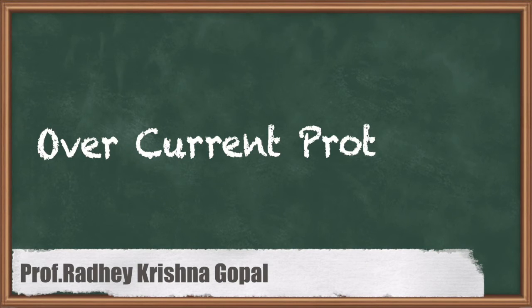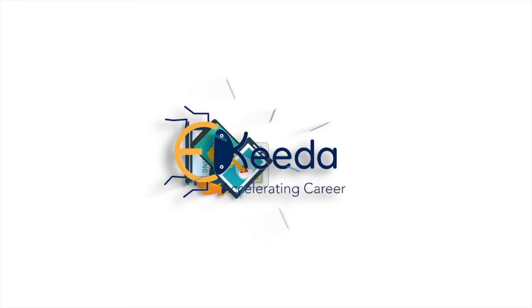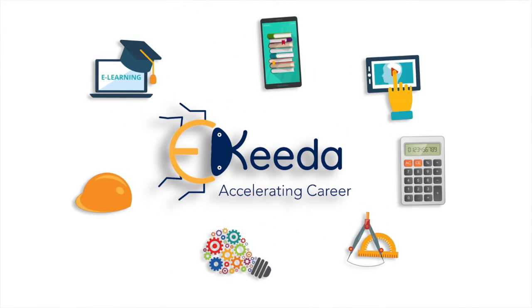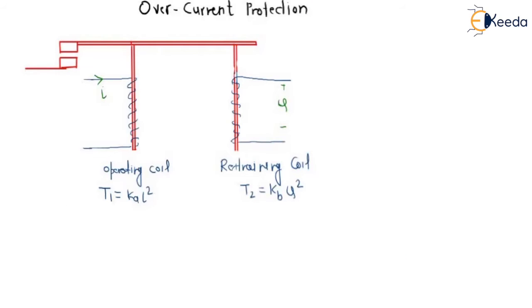Hello friends, now we are studying overcurrent protection. So before understanding the concept of overcurrent protection, let us understand the basic details of it. In overcurrent protection, we will use a balance beam relay. This is a combination in which in one coil the operating torque is provided, and in the other coil the restraining torque is provided.